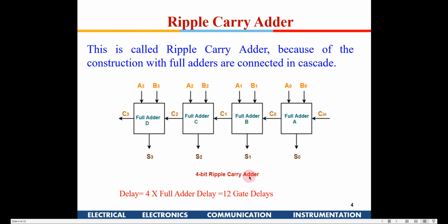Okay, now if you see the delay of this adder, you could say there are 1, 2, 3, 4 adders and a 4 into full adder delay, because finally this output has to come, right? So this output depends on the input which is coming from here, and this again depends on the input which is coming here. So this has to get generated, then this adder has to take this into consideration and compute and give a fresh output here.